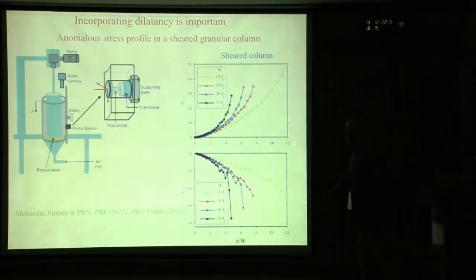and this was in these two papers. All components of the stress, the magnitudes increase exponentially with depth. Okay, and the shear stress changed sign. I mean the vertical shear stress on the outer cylinder. So it was positive initially, and the moment we started shearing it, it changed sign. Okay, and at that time we had no idea what the reasons were for this.